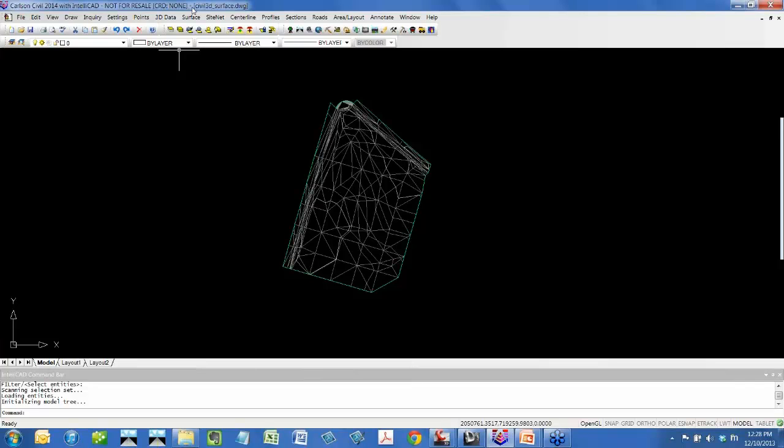I check on this. Of course, I've got a current subscription for Civil 3D, and I always double check with them. Once a year, I send an email off through the portal, through the Civil 3D tech support, and ask, please tell me if there's a better way to get data from one version of Civil 3D to the other, or out to another file. Anything better than Land XML? And the answer again this year was no. But the other thing it's always good to ask about, because with Civil 3D you've got all the styles. Like I said earlier, you've got a profile, you've also got a profile view. And it's my understanding that the profile views don't come over from Civil 3D, but that's definitely something to confirm.